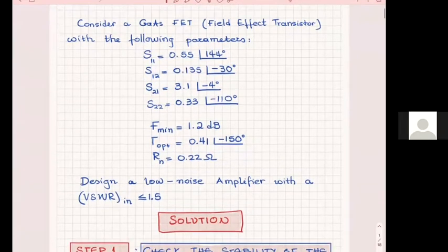Now this low noise amplifier, obviously we want low noise, and always in a low noise amplifier, I have to tell you, you will try to get the highest possible gain for the low noise that has been specified for you. You can never exceed a gain in an amplifier. Now, sometimes people will also give you a maximum gain just in case. I don't know, maybe how the transistor that they will give you to incorporate what characteristics will have. I don't know what later in the system, what kind of other conditions exist or limitations.